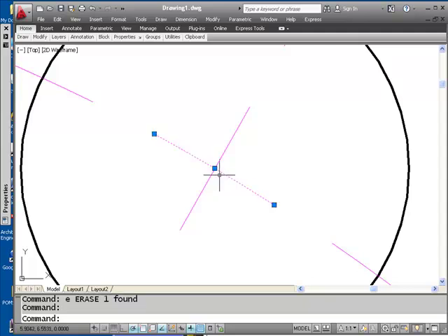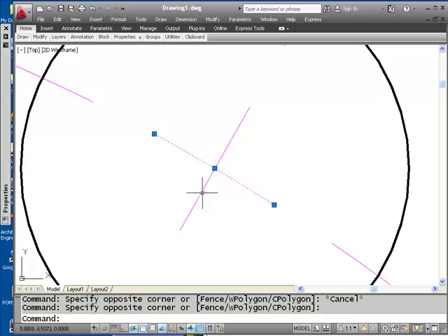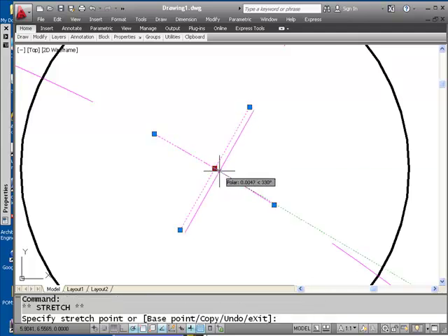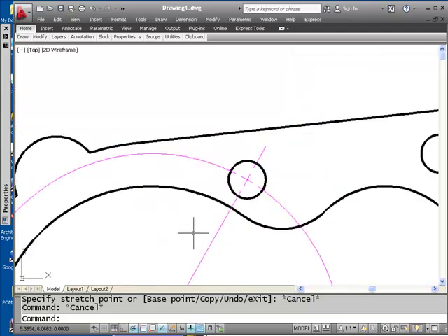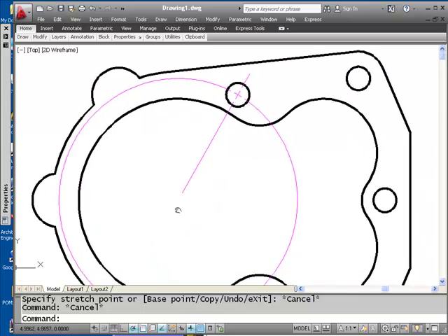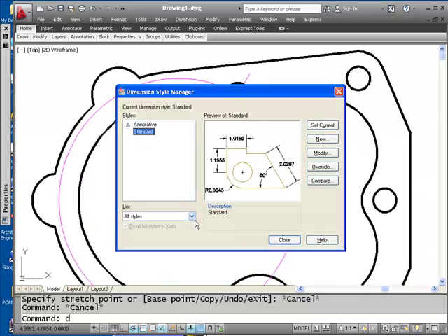That is an arc. You can tell if I try to change it. That's a straight line. You can tell on that if I try to change it. You want a straight line and an arc combo, and I want that size to match the size of everything else I do. Just make it clear what that is. I'm going to go into the Dimension Style Manager by typing the letter D, and I'm going to just modify the existing style. I'm going to give it a name first.